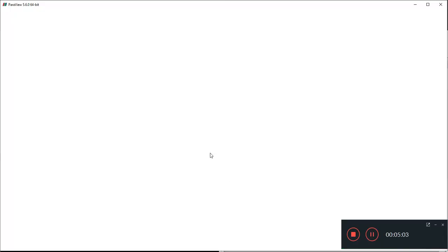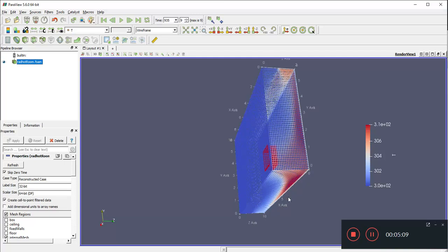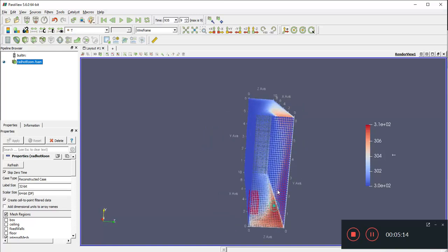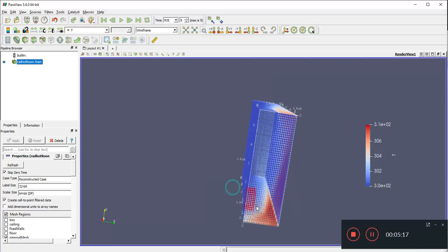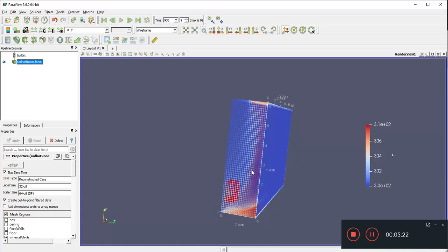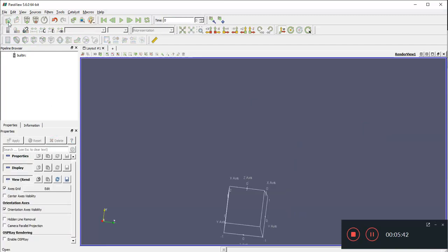And of course, whatever evolution of, for example, the hot room you're seeing here, this is just based on the iterations that the solver is running. It doesn't mean that the state is changing. Steady state is supposed to be constant with time. So what you're seeing in this time here just means it's the iteration. The solver is taking more steps to solve a new temperature field, and this is what you get. So let's take a look at the solar car.